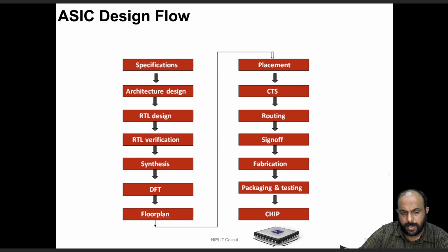Verification is essentially checking the conformance of the design to the specification independent of the designers. The designers have already understood the specification and designed something, but they might be missing certain corner cases, certain examples of inputs, upon application of which the design may malfunction. So the work of the RTL verification engineer is to debug the design at a much more exhaustive level that is not possible at the design level.